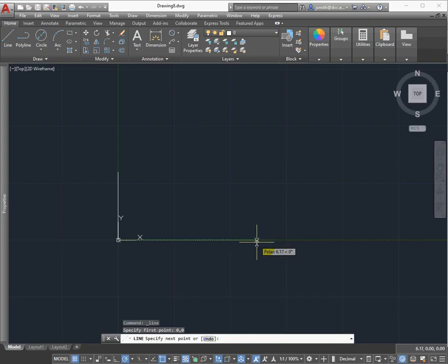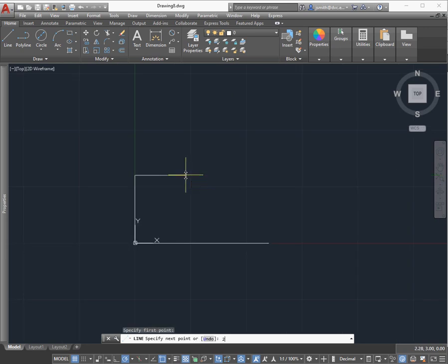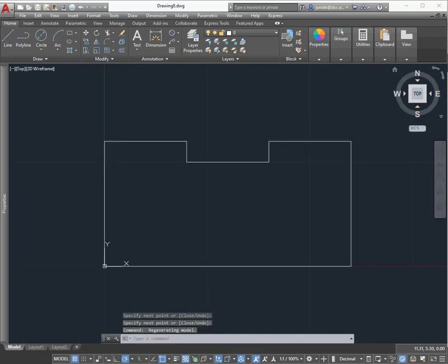All right, so then I'll take that line, start at 0, 0 again, and type in 6, push enter, and then I have half of it built here. My snap setting is already selected, so it's going to snap, and I'll move that out to the right. This time I'm going to go 2 inches, because I'm following the Spencer design part, and come down 0.5 inches. I'll type that in and push enter. Then I'll move my mouse to the right. Looking at my drawing, it goes over 2 inches. I'll type in 2, come up 0.5 and go over 2 inches. Then I can either type it or just snap and push enter.